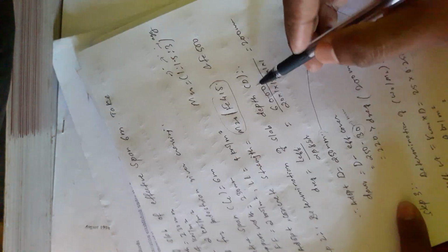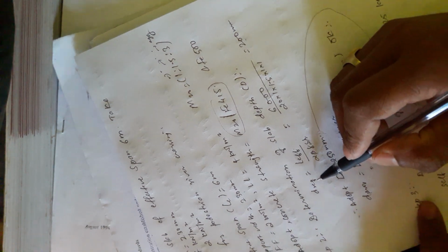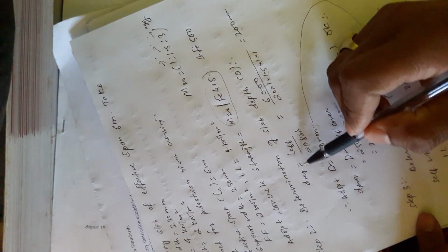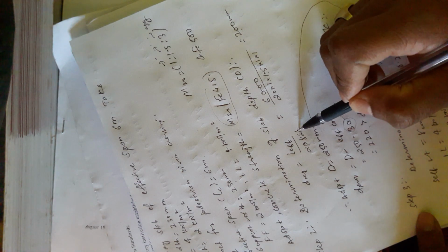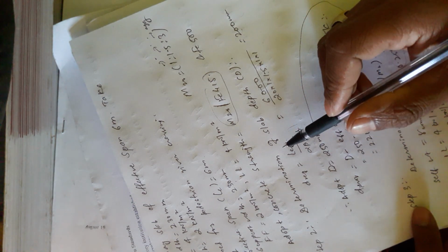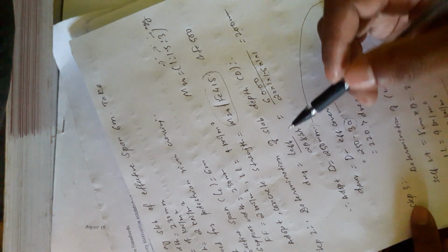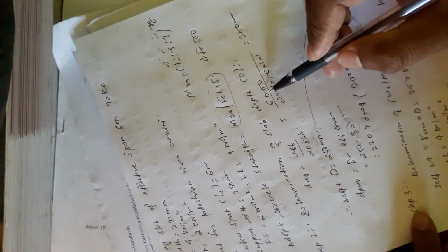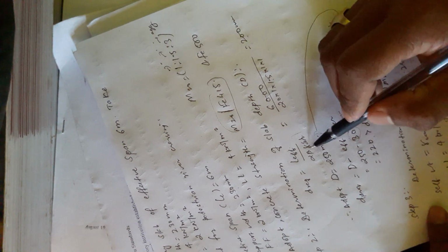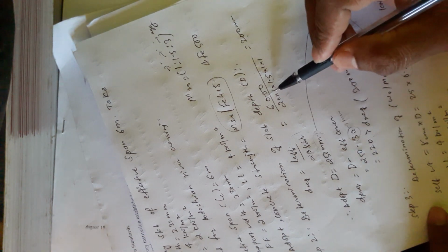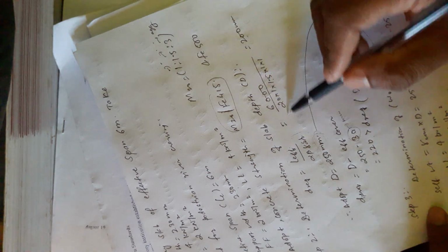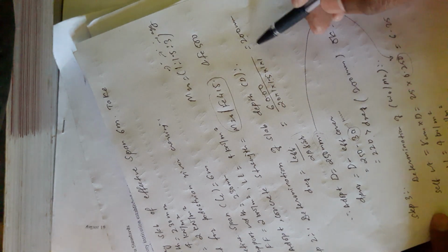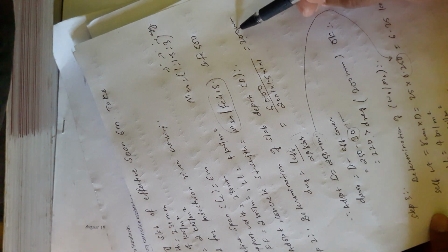Step 2 is the determination of slab depth, which is capital D. So D required is given by L effective by alpha, beta, gamma, delta, lambda. This is the formula you need to remember, or it is also available in code IS 456. So our L effective is 6000 by alpha, where the value of alpha is 20, beta 1, gamma 1.5, delta 1 and lambda 1, which is also available from the code. And by solving this we get 200 mm.